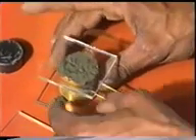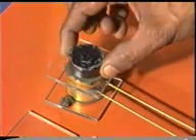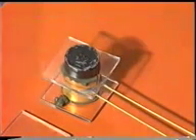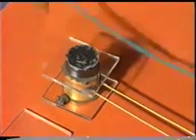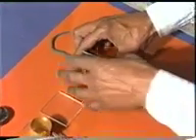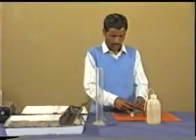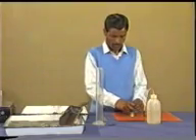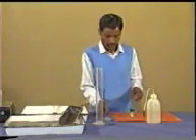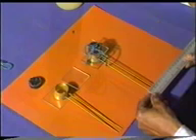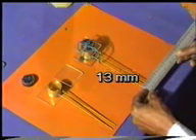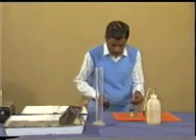Now cover the filled up mold with another glass plate and place a 50-gram weight on this plate. Tie up the whole assembly with a thread. Now measure the distance between the tips of the indicators, which is 13 millimeter in this case.